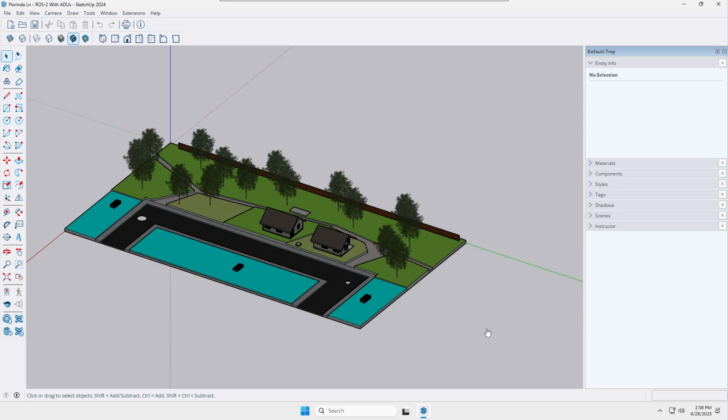In SketchUp, we may want to see a section again of part of our work. So let's see how we make a section in SketchUp. Here's a typical little SketchUp drawing, and here is the section plane command. I have it in the large tool set.